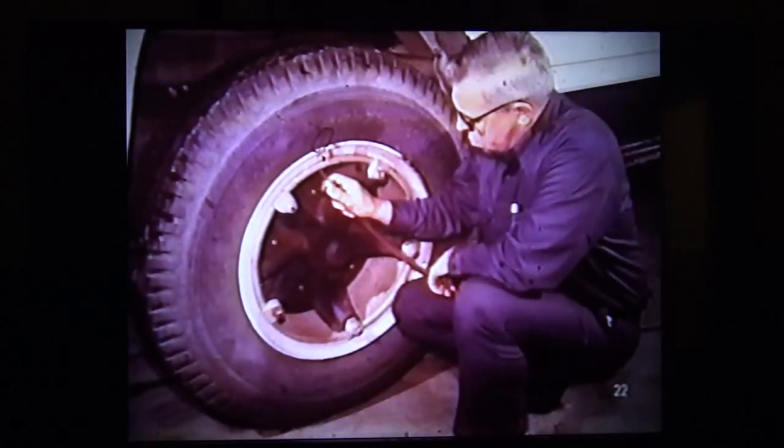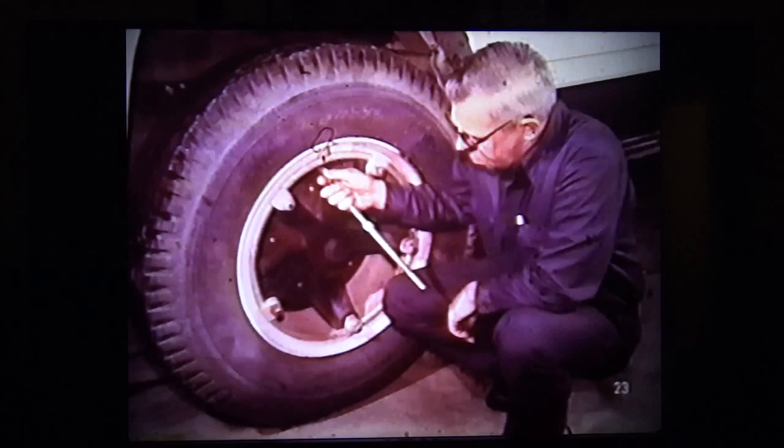Next, check and adjust tire pressures for the load being carried. If the tires are cold, you can inflate them to the required pressures. If they are warm, the only thing you can do is equalize the pressures. If the unit is not equipped with a tachometer, install a portable tach. It will be used during the test procedure to determine the RPM range in which the vibration occurs.